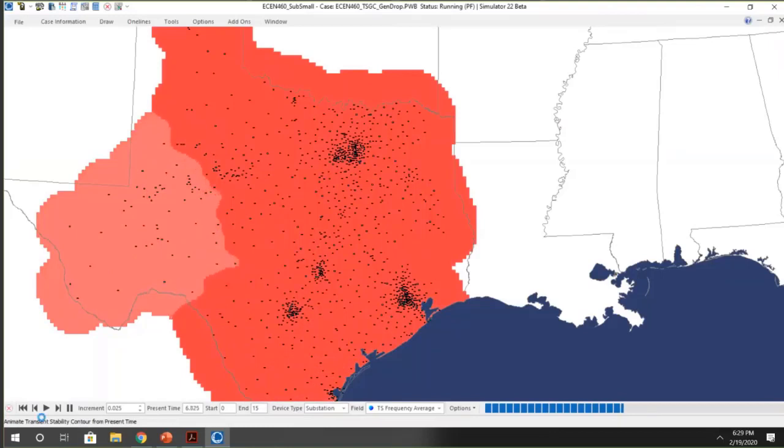After you play with this for a couple weeks, you're going to eventually call and ask a question, and the answer will be disappointing to you. Because a lot of people are like, "Oh, this is cool. I can just do contour right through, and Simulator will bring over all the generator outputs, all the line flows, all the voltages, all the frequencies at each time step." It's like, no, we're not doing that. All I'm doing is bringing over the one value that's your contour. So if I were to zoom in here and look at a voltage, it would not be changing.